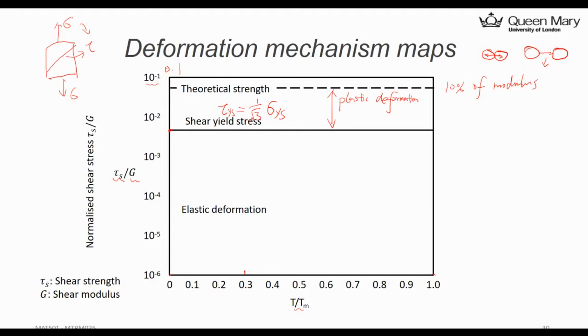And let's look at some special regions. Like I said, plastic deformation is basically governed by the dislocation of the material, doesn't matter what your temperature is. Whatever the temperature, once it has reached the plastic yield region, it is governed by dislocation slip. I will approach dislocation later on, so you will understand dislocation better.